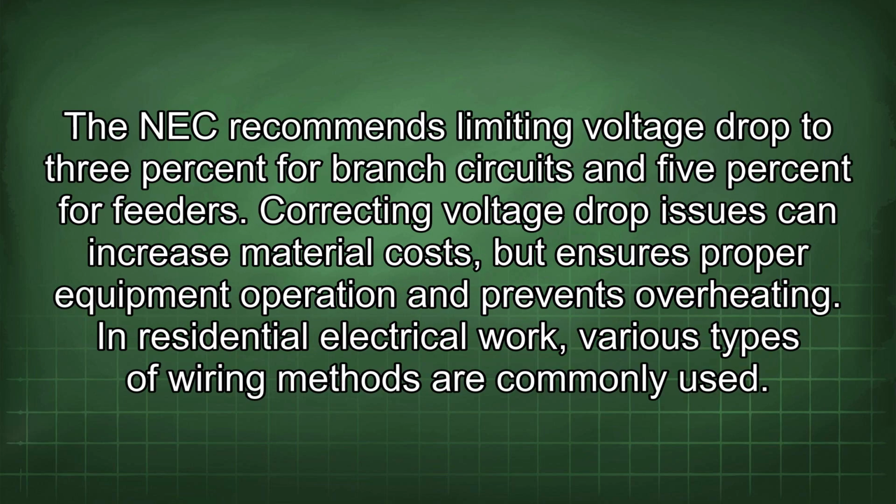The NEC recommends limiting voltage drop to 3% for branch circuits and 5% for feeders. Correcting voltage drop issues can increase material costs, but ensures proper equipment operation and prevents overheating. In residential electrical work, various types of wiring methods are commonly used.